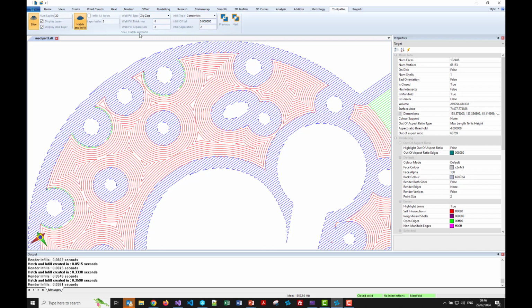The -1s, these are just things I put in my code. The defaults are not in the example code that we provide at the moment, and they're really just based on the maximum thickness, which is something Polygonica computes for you. So it's a very useful way of setting a default based on the maximum thickness of the profile. Obviously, in a real job, you would probably use physical parameters.